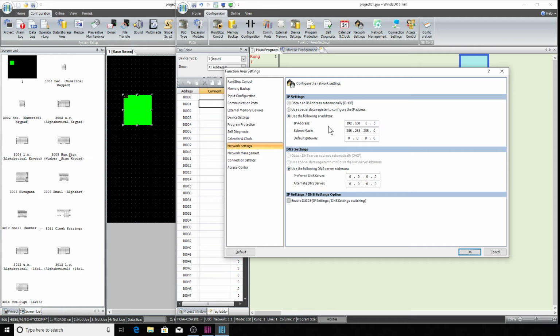See, here is our PLC IP address that it defaulted to over here. If you change it over here, you have to change it over here. Like if you're on a network, like I said, and you're changing it to match your network, yours might be 168.10 dot something, whatever it might be. You have to change this to match it as well as in here, so you know where for it to look to.